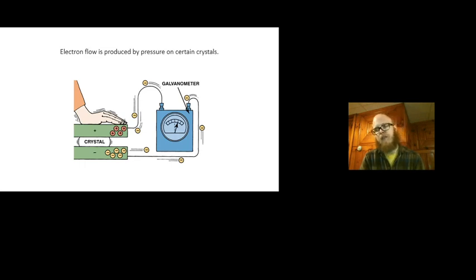That voltage shows up in a meter or in a computer, and the computer goes, "Oh, that's not good," and it retards ignition timing. It might mess with the fuel control a little bit, but it's trying to save the engine from cracked pistons, holes, and cracked heads.